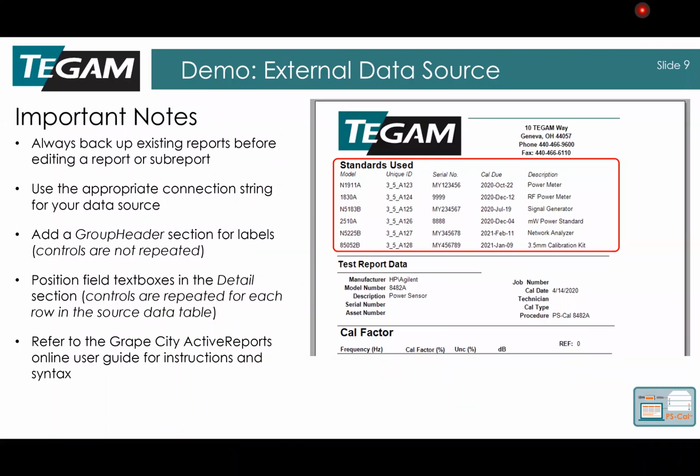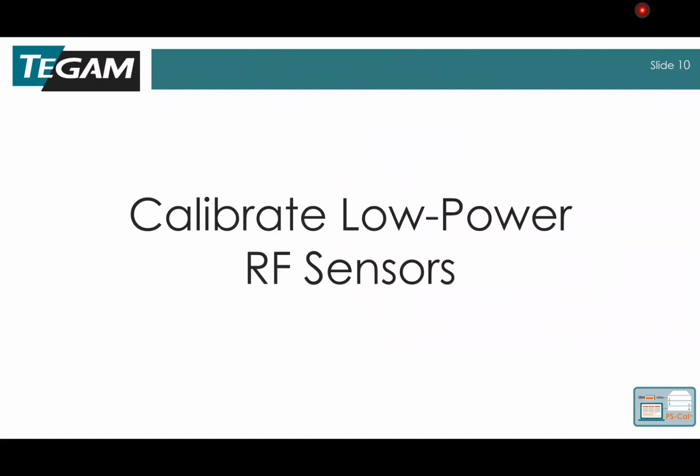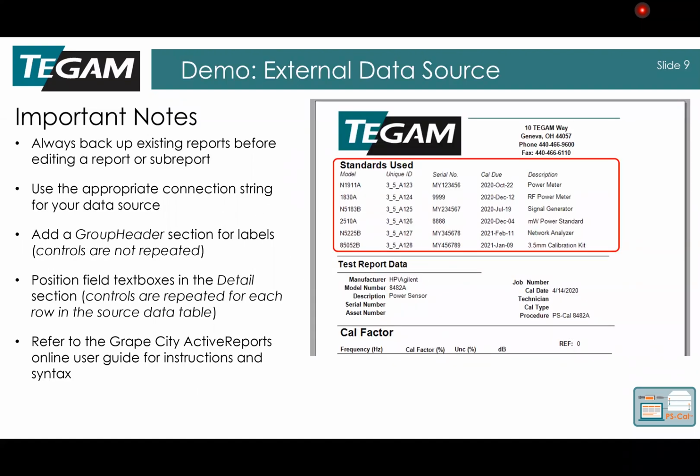There's a couple key points that I think are worth going through, and we'll try to do those fairly quickly. Important notes: always back up your existing reports before editing a new report or creating a new report. One of the things that I often recommend to folks, especially when I'm on site, helping them with their initial installation and system commissioning, often what I'll have them do is back up the entire reports folder. That's a safe way to make sure you have a backup of every report in there before you get into customizing various reports.